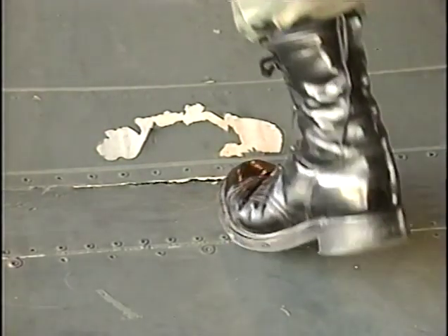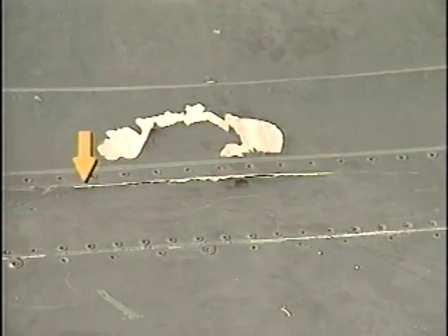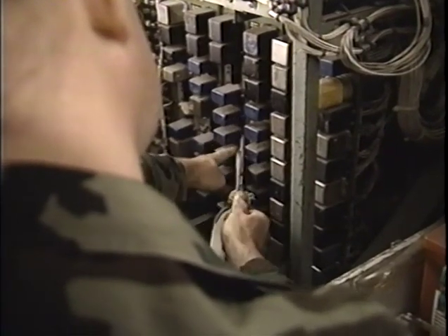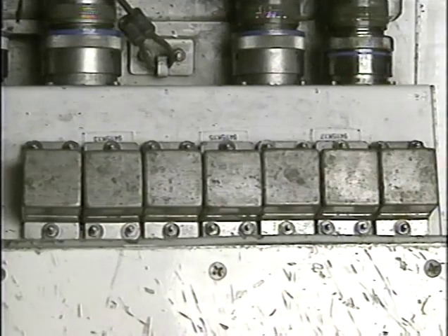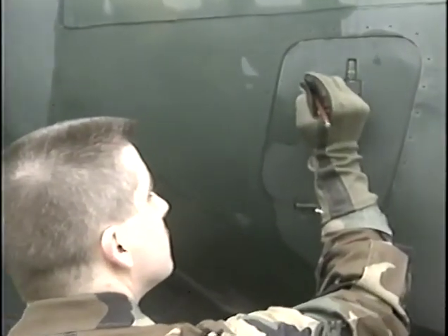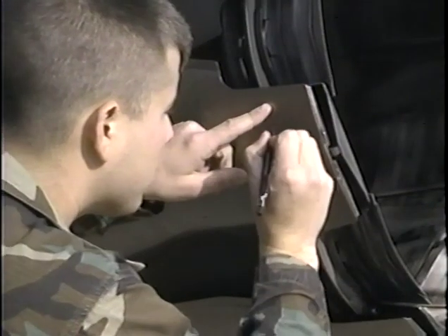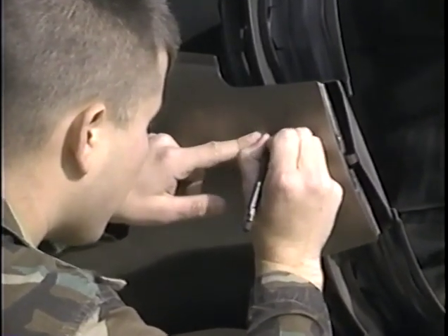This has caused structural damage to many areas not designed for the added weight. In addition, it allows moisture to enter these areas. Circuit breaker assemblies need to be cleaned regularly to prevent dust and dirt from building up. Moisture also has a tendency to accumulate in these areas and has been the cause of electrical short circuits and failures. Using graphite marking media such as lead pencils for marking on any metal surface can promote accelerated corrosion. Chalk or grease china markers are the preferred method.